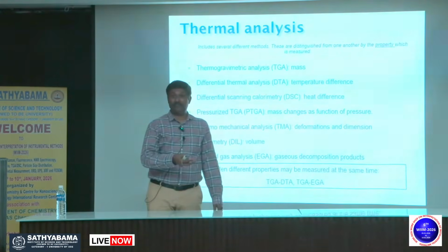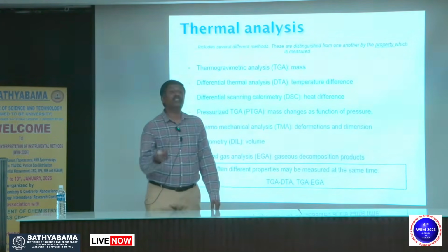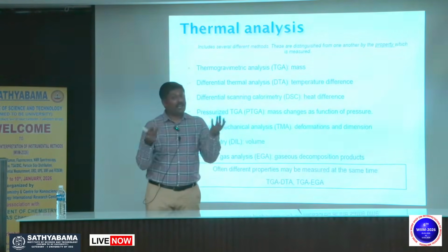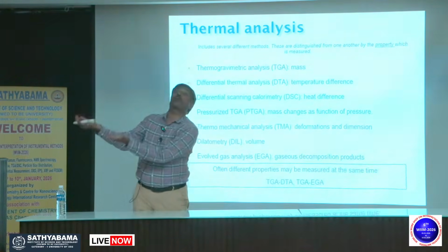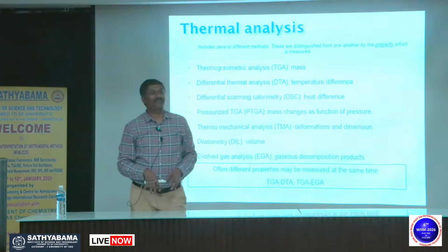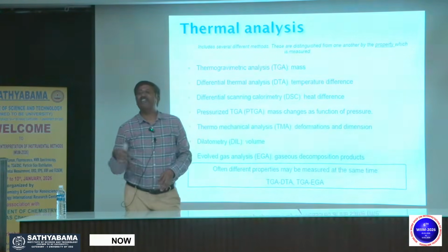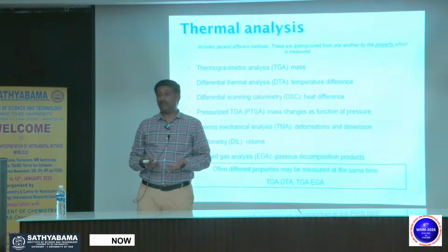TGA-MS, TGA-DSC. You insert the sample once, it degrades. How much it degrades I also want to know. What the degraded products are I also want to know, and how much of the products there are. TGA-MS-MS, so that much advancement has happened.